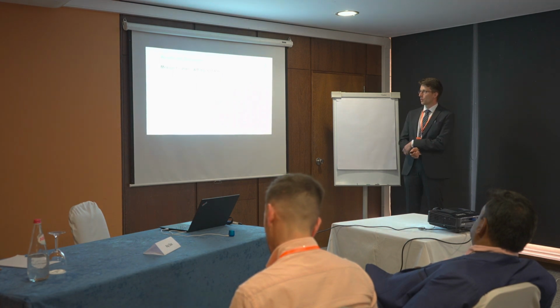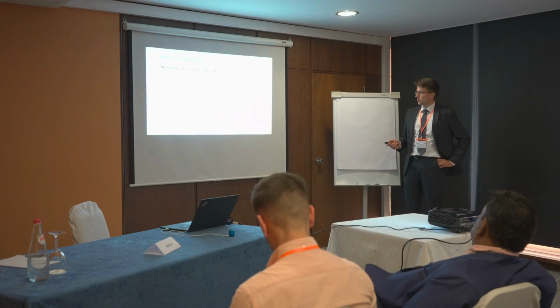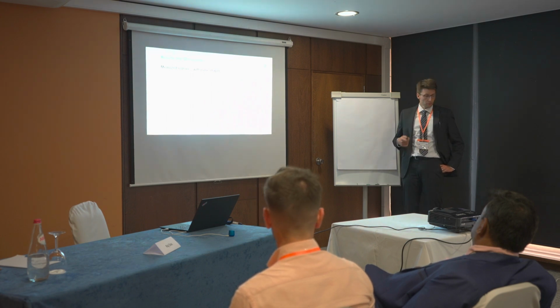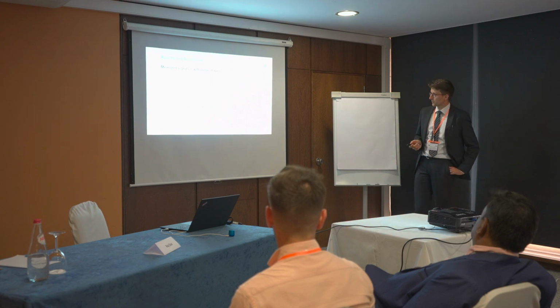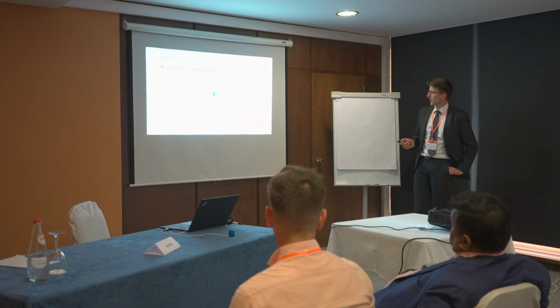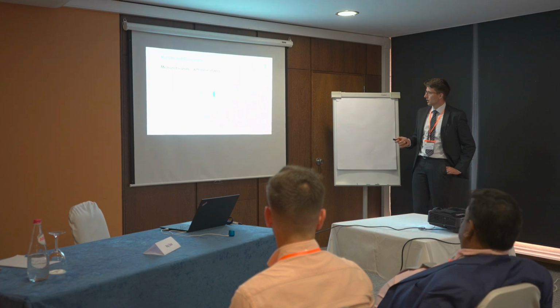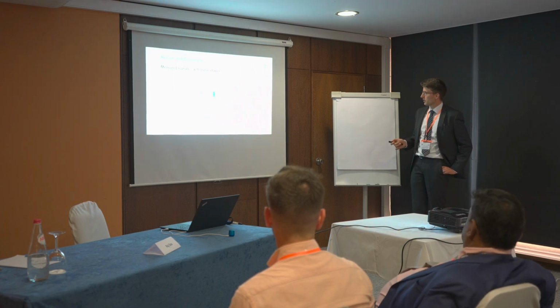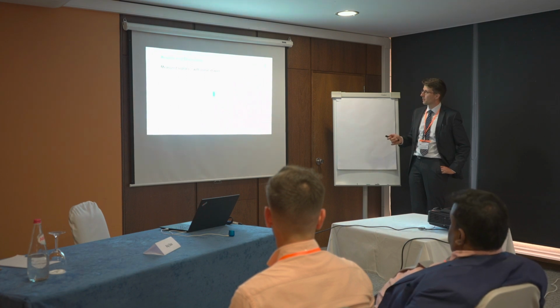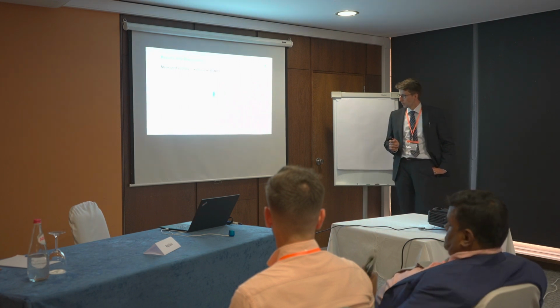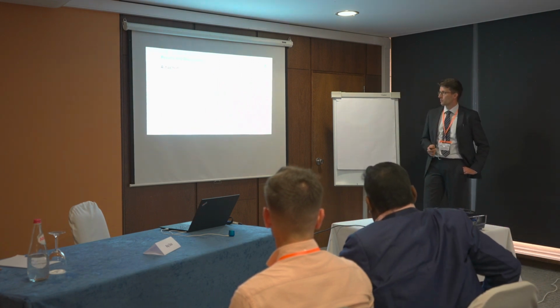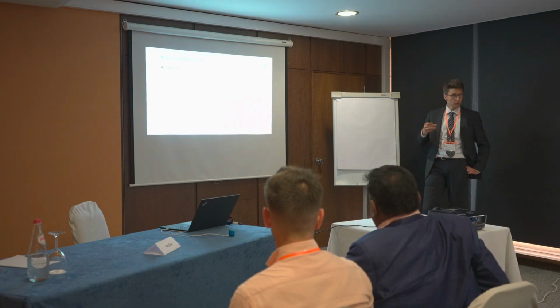In the next slide, we use a pulse shaper, a quite thick pulse shaper, which generates a quite long rise time of the incident pulse, which of course much lowers the dispersion effects. We also measured the displacement here, and then we can have a look at the measured displacement and the calculated displacement, and we get the same slope, also with the same equation here.